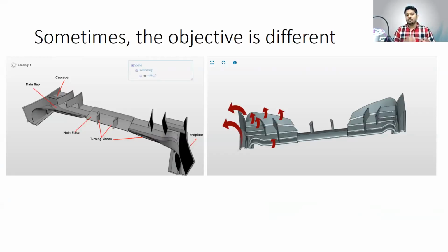So you take a truck and rotate it by 10-15 degrees, which is what you call yaw, and then you perform the same simulations. The reason you're doing this is to understand the overall design and the effect it has on its aerodynamic performance. You have to look at the entire picture.